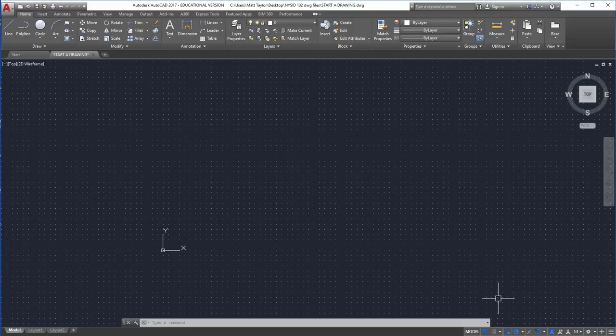Okay, next one. These two buttons here are grid mode and snap mode. I'll talk about snap mode in the future. That one's going to be turned off. Grid mode is going to be on. So this needs to be on, this will be off, and the downward facing arrow next to it, if you click on that, will bring you to a menu, and you'll see polar snap is on. That's the snap mode. And grid snap is on. That's the O snap. No idea why they give it different names here. It's just confusing. But that's what we want.